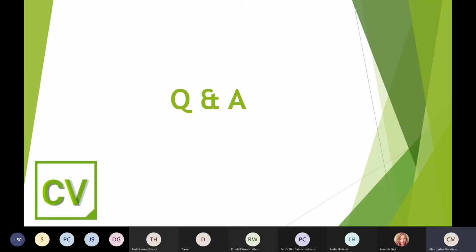Now, because I said you have the shape editor included in the door editor, so you could basically design your very own style where you add your operation and your shape and make it parametric. So you could use those old templates, but if it's something more complex that's not available in the list, you will basically create the shape, make it parametric, and then associate a toolpath to it.